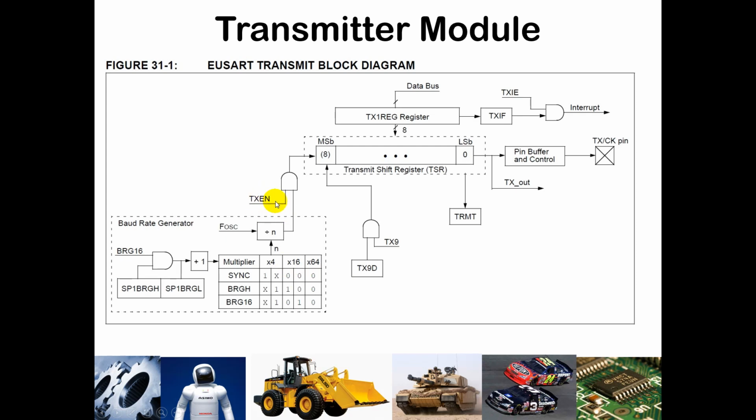And then what happens is when you're ready to transmit data, you will use the TXREG. That is the register where you are going to set up the 8 bits that you wish to transmit. You can also do 9-bit mode, and so that comes in down here if you want to send a 9th bit, but we will use 8-bit data transmission.